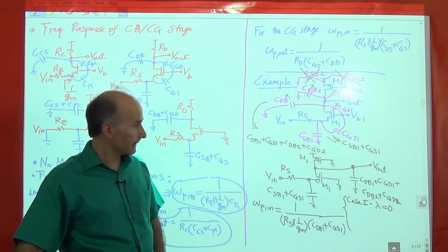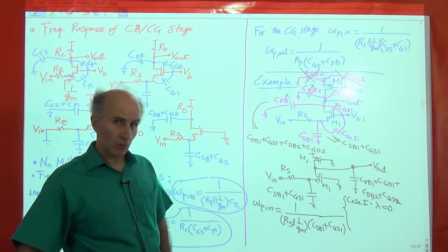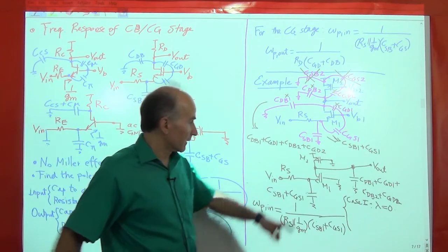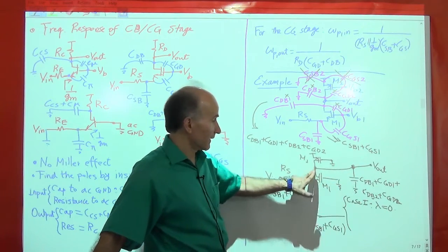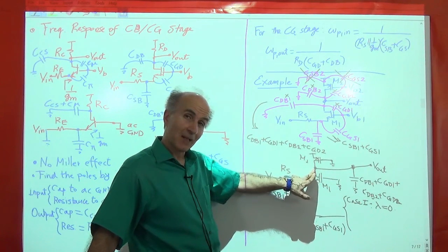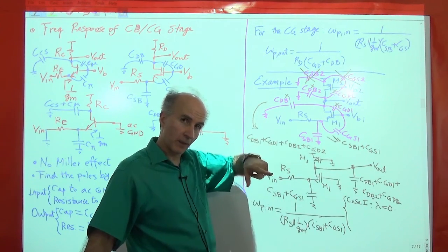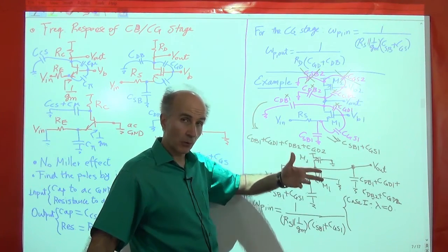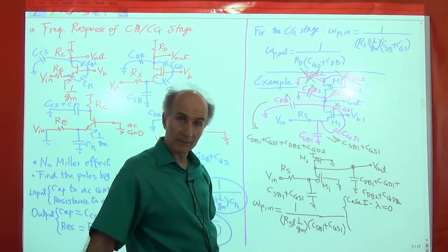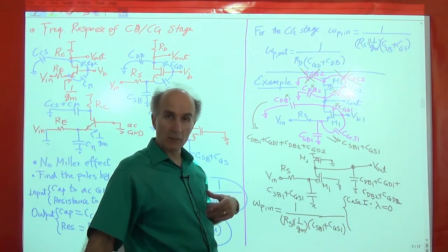All right, okay, so then what do we do here? Do we have a problem? We sort of have a problem, right? Because the capacitance is given, the resistance is infinite. So then where's the pole frequency? The pole frequency would be 1 divided by infinite resistance times capacitance. So the pole would be at 0 frequency. Is that a meaningful thing? In some cases it is meaningful.